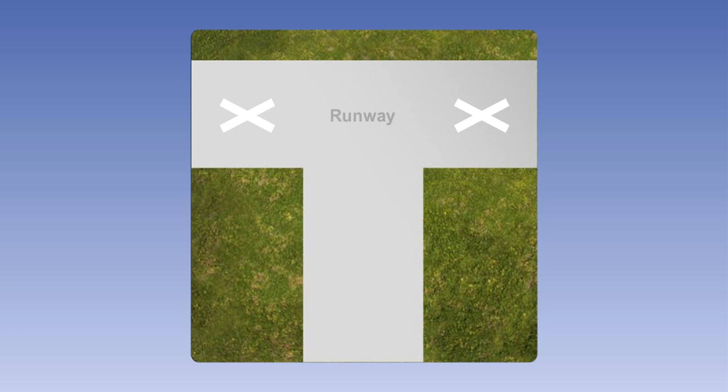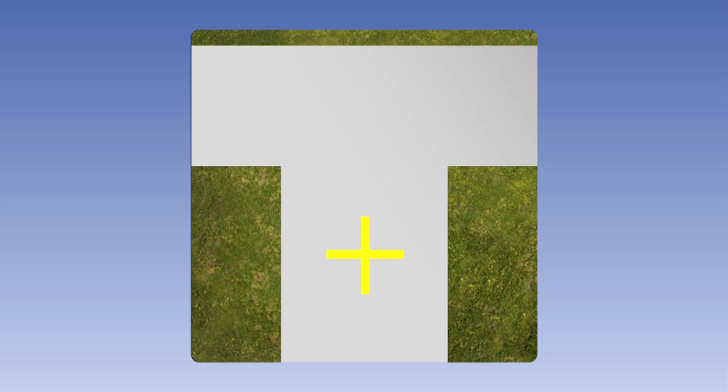On a runway, two or more white crosses indicate that the section of the runway is unfit for aircraft movement and is not to be used by aircraft in any circumstances. A yellow cross indicates that that portion of the taxiway up to the next standard marking is unfit for use by aircraft. On a selected part of the aerodrome, a yellow marker, in the shape of a St. George's cross, indicates an area reserved for the dropping of tow ropes or similar articles.